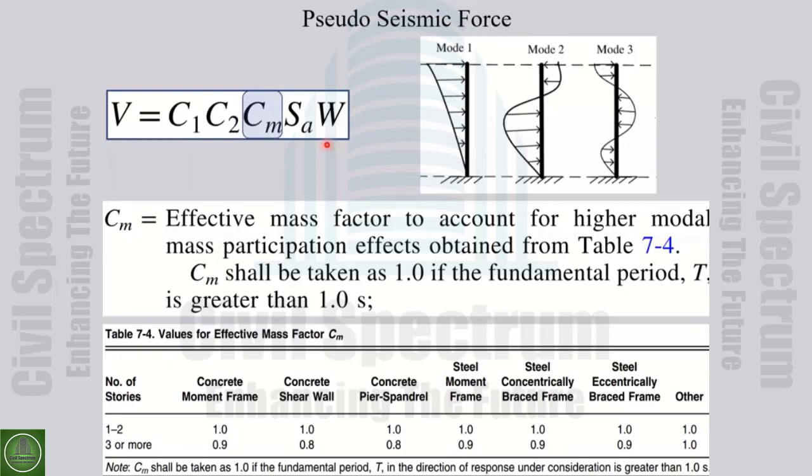We can see that due to the pinching behavior in the hysteresis curve, due to inadequate detailing, the amount of energy dissipated is less, and the building gets more displacement in this badly detailed building.